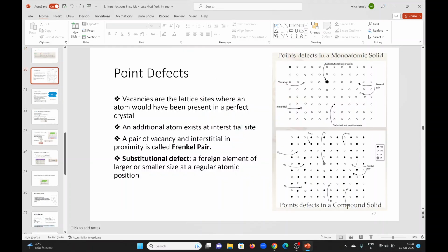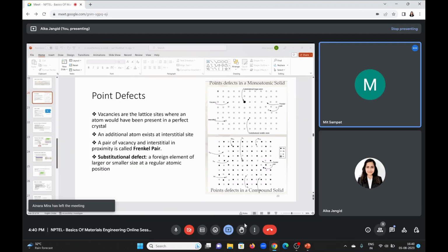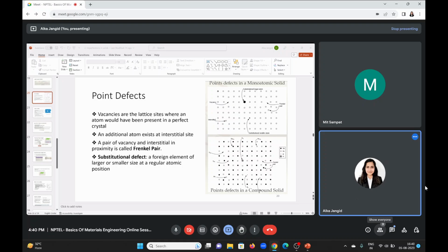To ask, what causes these stacking faults? During manufacturing, there may be stacking faults present. Like one plane is missing in some area, not the entire area, just in some area. There might be formation of vacancies. Vacancies might cluster at a plane, then that plane will be absorbed from that particular area. Then in that area, you'll have a stacking fault.